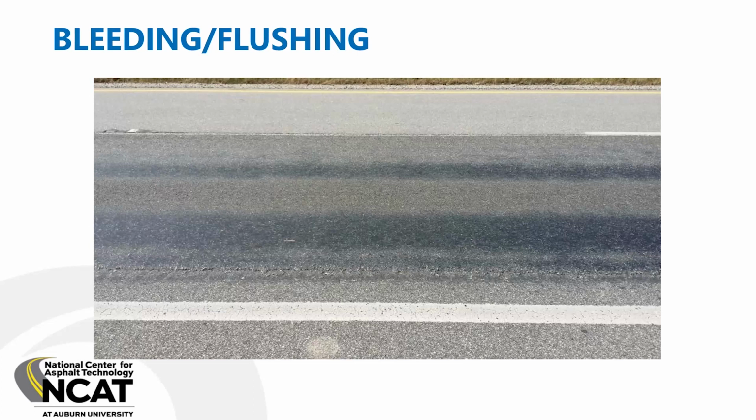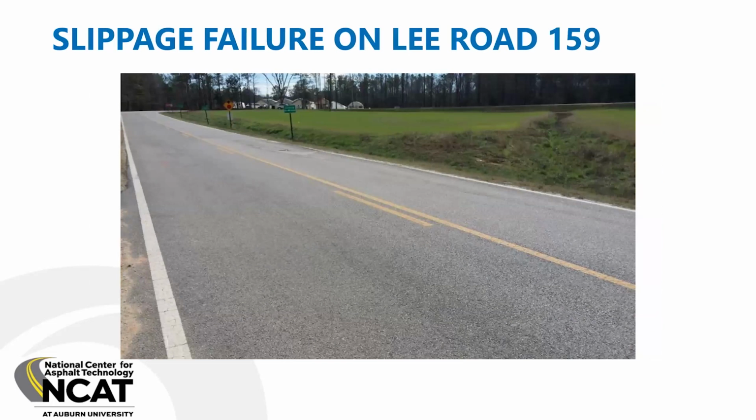That's one of those treatments. The multi-layer chip seals can be an outstanding treatment, but it does better on the low volume roads than it does on the high volume roads because of the bleeding and the flushing.